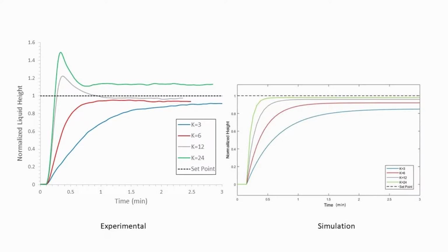The results also differ in that the controller gain of 24% valve opening per inch has a much smaller offset in the simulated response to go along with what was expected originally.